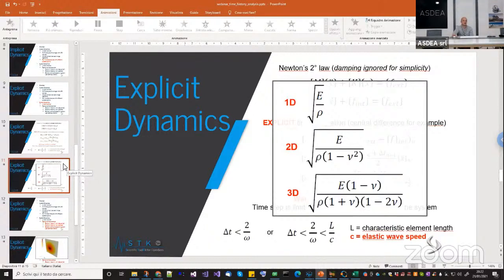When we do explicit analysis, do we always set the system as diagonal? No, you are not forced to use diagonal, because a diagonal matrix is a subset of a general matrix. It is simply faster. For being diagonal, you need to have only the mass matrix. If you include damping, and it is only proportional to mass, it will be diagonal. If it is proportional also to stiffness, it will not be diagonal. The other problem is that the diagonal solver is only available for sequential OpenSees. There is a diagonal solver for OpenSeesMP that I said is not working, and in the next days I will try to find a solution for that.